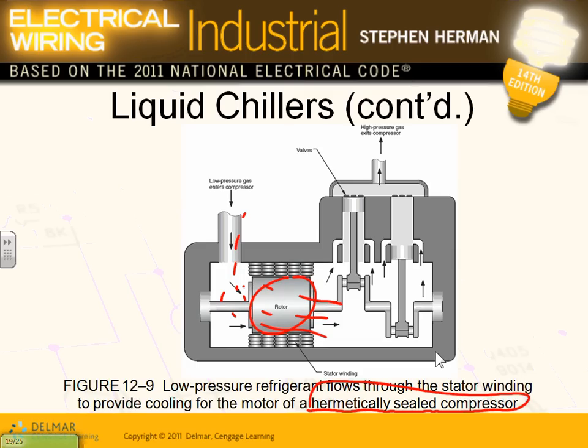If you have some type of forced cooling system in your machine, guys, you can overload your equipment. I can make a 15 horsepower motor work a lot harder and give me a lot more power if I can chill it. Force it. It's not just by the air being around it.